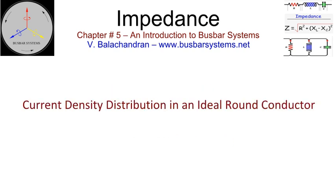Current density distribution in ideal round conductor. It is interesting to observe the current distribution in a round conductor subjected to the combination of skin effect and proximity effect. If the currents flow in the same direction, as in the case of two conductors in parallel of the same phase, then they tend to concentrate at the farther end of the conductors. If they are in the opposite direction, as in the case of go and return conductors in a single-phase system, then they tend to concentrate closer to each other.